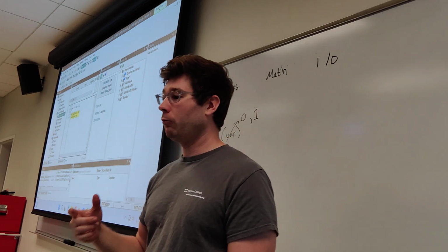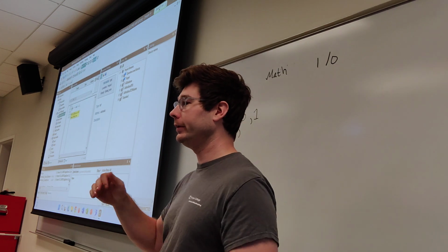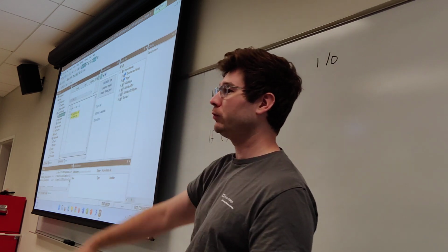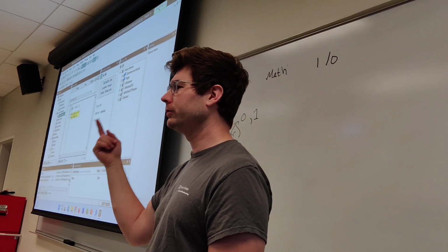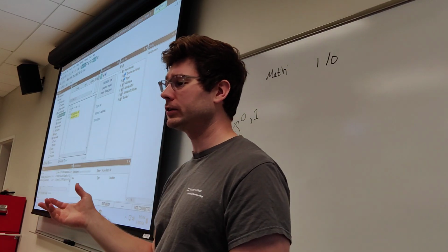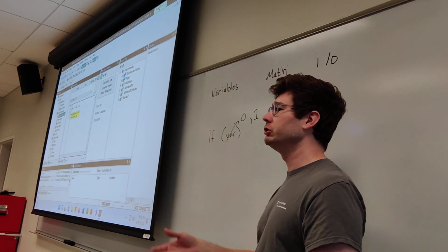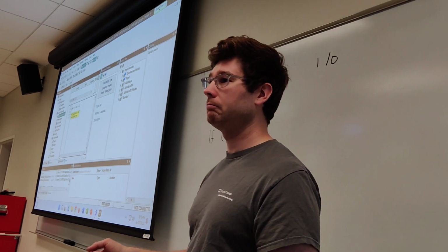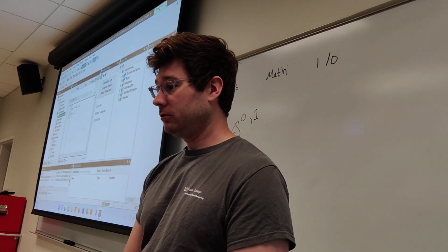You might imagine that'll keep increasing count over and over until it hits a theoretical upper limit and wraps back around. It goes to negative, I think, or 0, and then just keeps on counting. That's all the program does. It's essentially a canary that shows us that the PLC is still running and doing something at all times. Okay, default program.